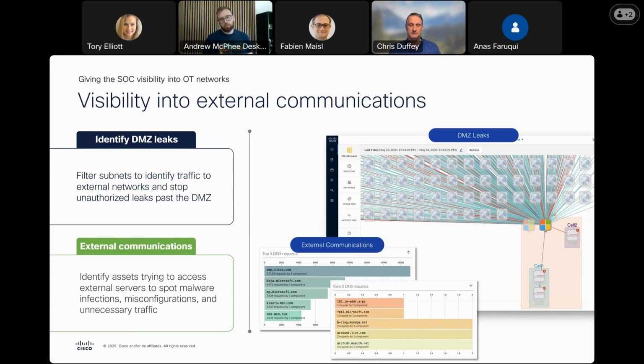That's not air-gapped. There are always paths from the internet in, and CyberVision is the type of tool that will show you that these paths exist, because that workstation isn't air-gapped, and that workstation speaks to the PLC, so therefore your PLC is not air-gapped. Definitions vary depending on customers, but how do you know what's happening in your network? Well, you need visibility to understand truly what's happening on your network.